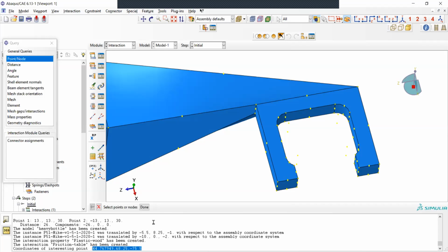I will explain in a second why. So now I got the data, I select this data here, and I click Control Copy. I'm just copying those coordinates. And I go to create reference point, and I paste here those coordinates. And then I change the Z value to 63.5. And I hope I'm not wrong. Now, if I click Enter, I should see a dot in the center. There is one, but it's too yellow, and the background is white. If I click here, I assume you can see it. It says reference point 1, and there's the X.